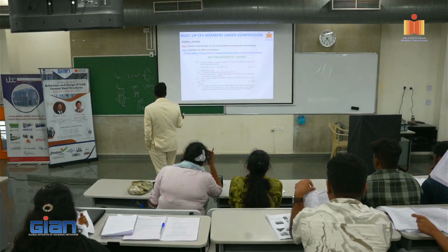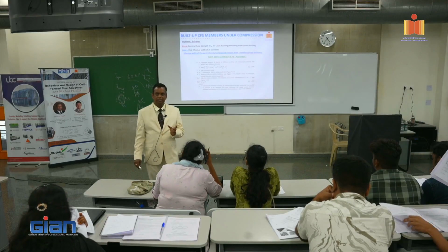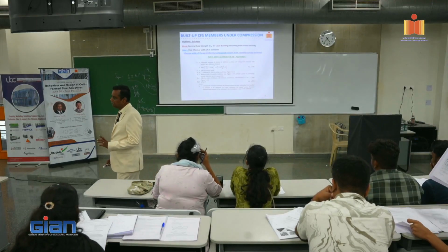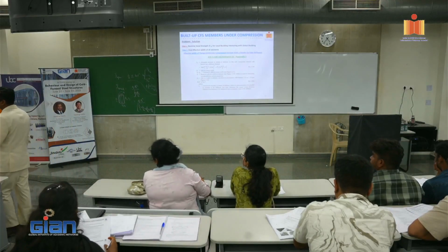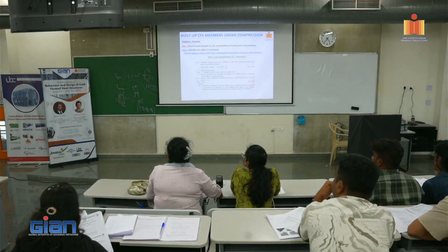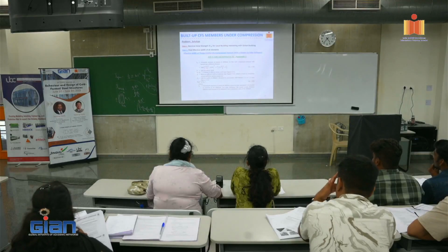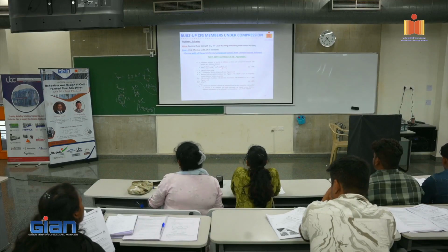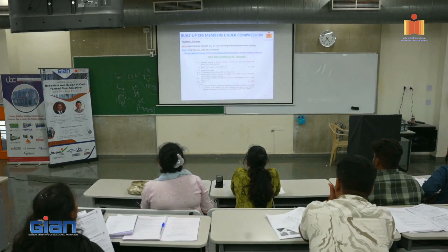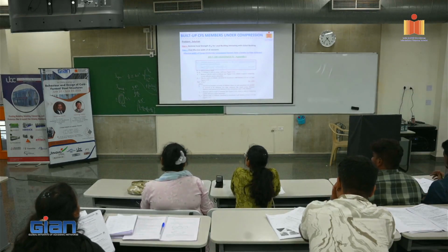We have to find out one more thing. What is the moment of inertia that is required, and what is the moment of inertia that we have supplied? Ia is the moment of inertia that is required to act as a stiffener, right? That is a bigger equation here. This is 399 t^4 times (W/t / S - 0.328) cubed, and it should be less than or equal to t^4 times (115 W/t / S + 5). So we calculate this one, that is the required moment of inertia.